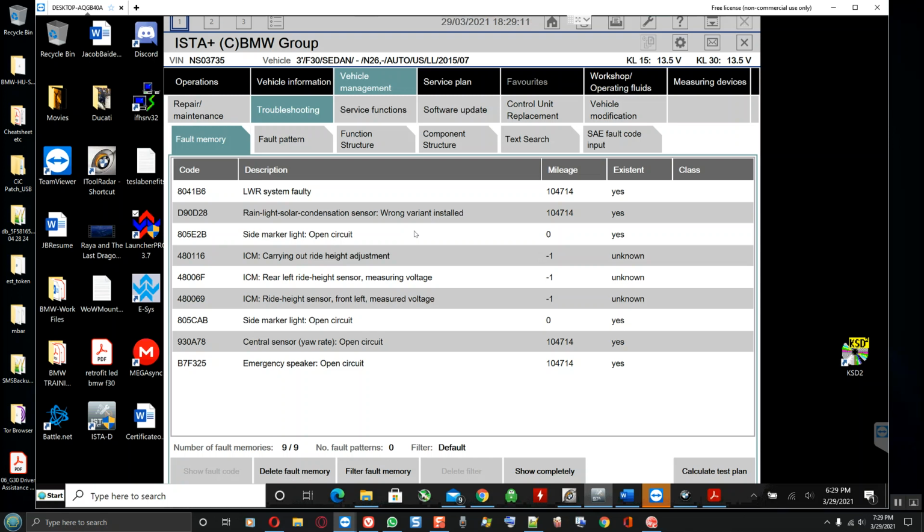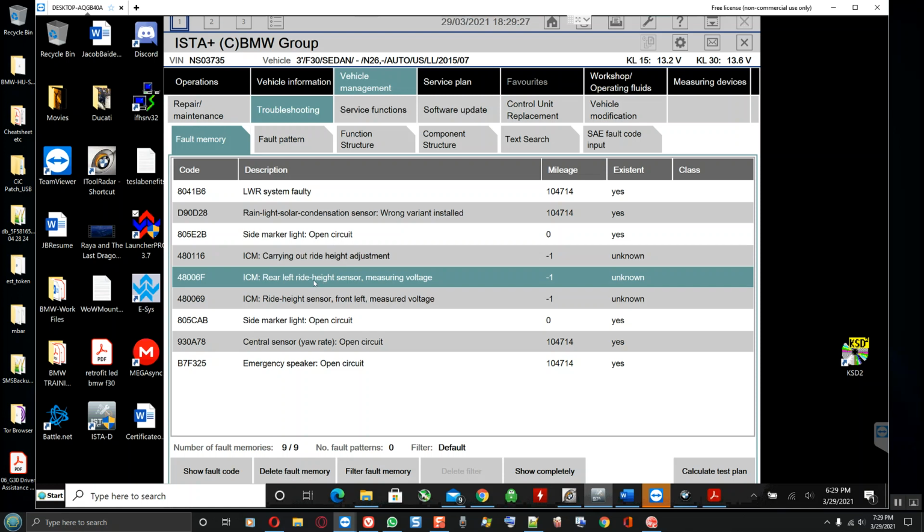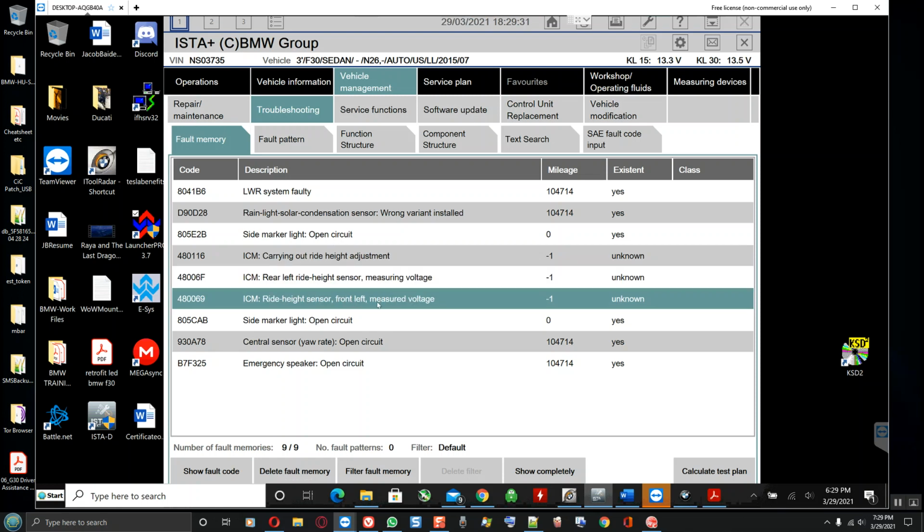Hello? Josh? Oh, you're here. Alright, cool. The airbag here, we have the ICM here. This works with the airbag and so on. We have to carry out right height sensor adjustment, left and right height sensor measuring voltage. The right height sensors aren't hooked up yet, so that's all those faults are. They have to be hooked up for the system to work with the airbag module, the ACM, the ACSM and the...